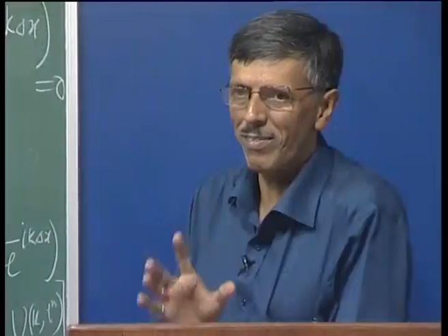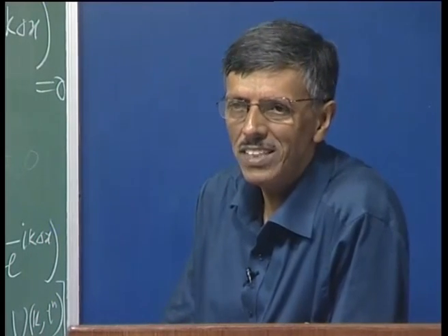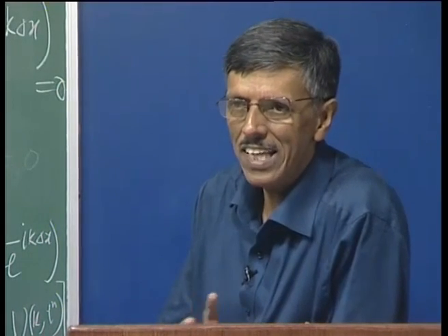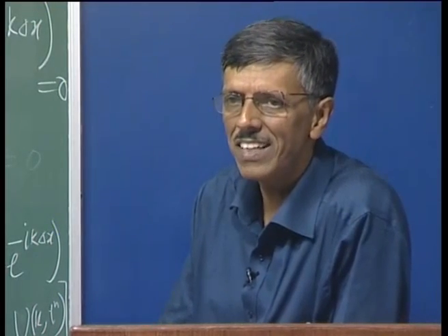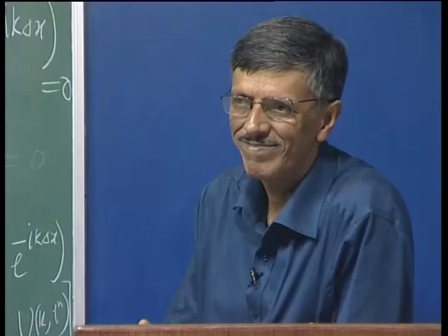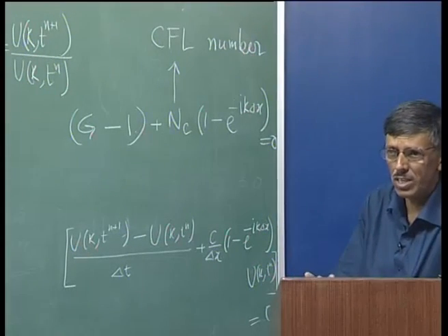So, what we have learned is that upwinding by itself is not bad, provided you do it physically, and here doing it physically is equivalent to taking n c equal to 1. There is nothing wrong with upwinding per se, but if you overdo it, say instead of taking n c, which means what? It is a measure of c times delta t. So, delta t tells you the time step that you are taking.